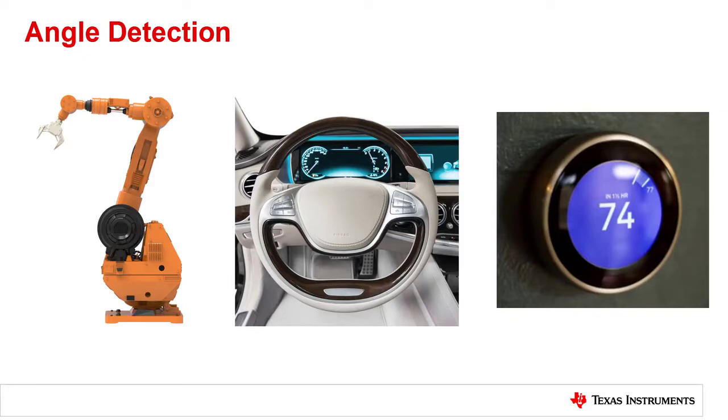Many applications rely on sensed position feedback to determine the state of the system. When the object is rotating, there are cases where incremental encoding does not provide enough resolution, or might not be able to detect the initial conditions at power on. Having the ability to define the absolute angle of the target, even at power up, provides more robust operation and